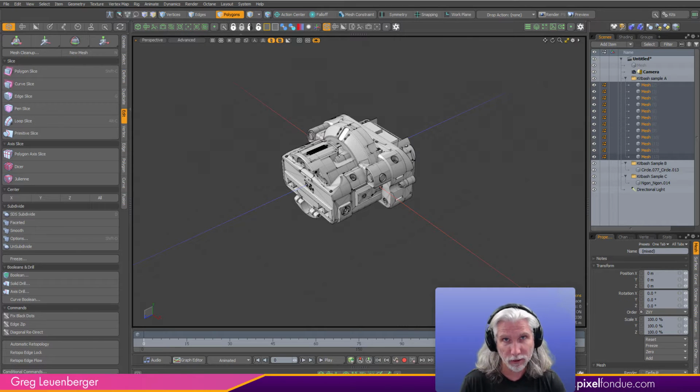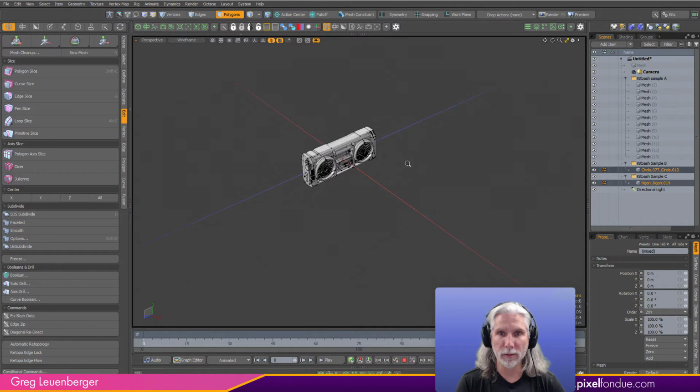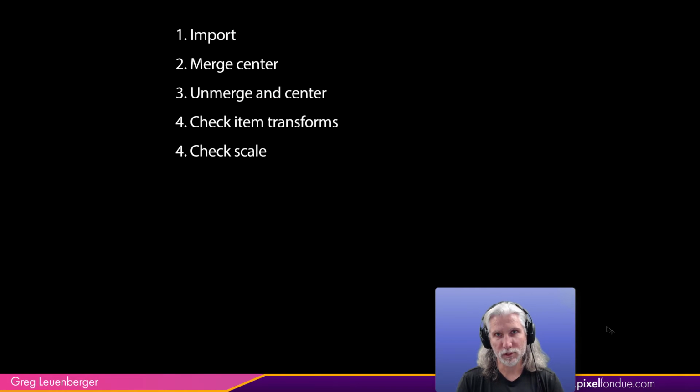Why is this so gigantic? Or why is this so small? Or why is this rotated around when I zeroed it out and now it's all like off axis? You just want to make sure all your transforms are at 0, your scale's at 100, so it's a nice, clean baseline asset. You can always go back in here and reset them all like that. These two as well, all zeroed out. Again, like I can reset them if I am worried about it. All right, I got my transforms taken care of.